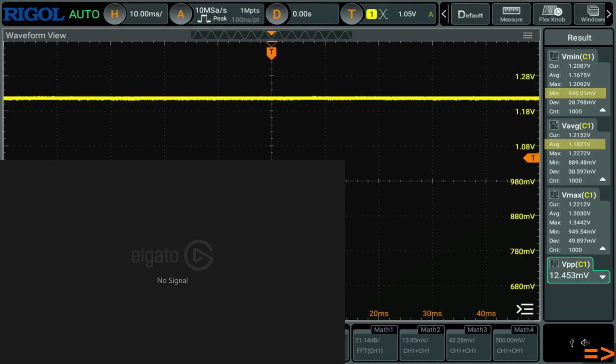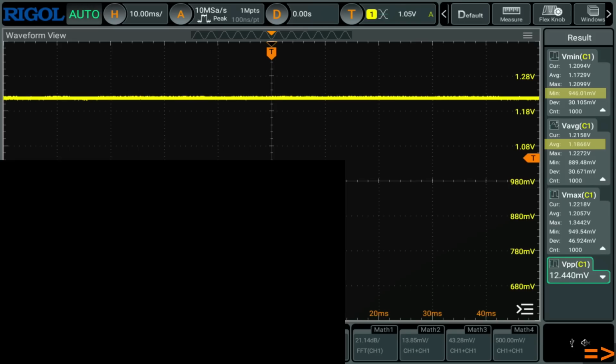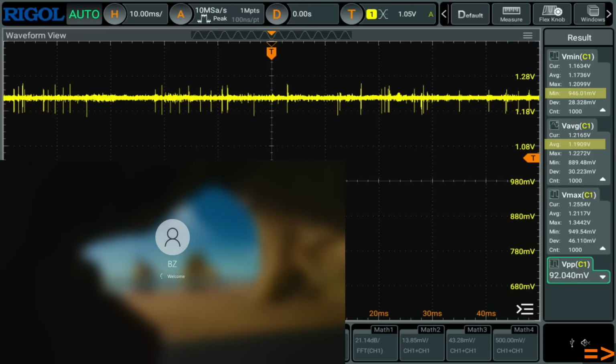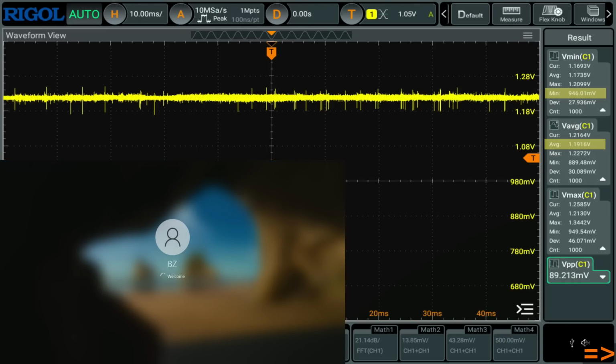is unusable. Yeah, that's kind of the nicest thing I can say about it. You do not want to have 110 millivolts of undershoot. That's just bad. Especially when you're measuring it from the back of the motherboard, where we're not even seeing the full extent of it. I'm not sure how much of it gets hidden by the impedance of the CPU socket, but certainly we are not seeing all of it.